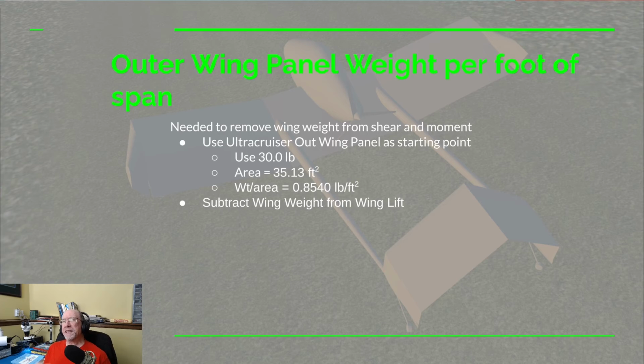I did a video recently that I put into a new playlist, which is a structural design playlist. It's more generalized structural design. And in that particular one, we used lift forces to calculate the shear and moment on a wing. Now, one thing we did not do in that video, because I was trying to keep it simple, is that we did not subtract the weight of the wing from our lift. That's something we can do, which is really nice because it makes our forces a little bit less. That's because the weight of the wing is not transferred to any other part of the airplane. So it does not contribute to shear and it does not contribute to moment.